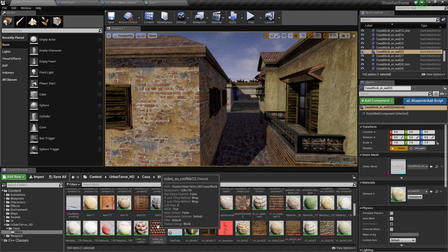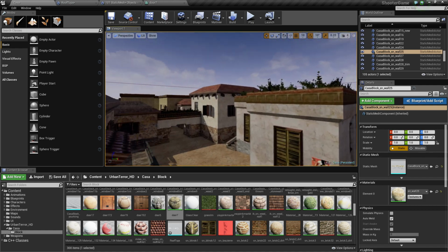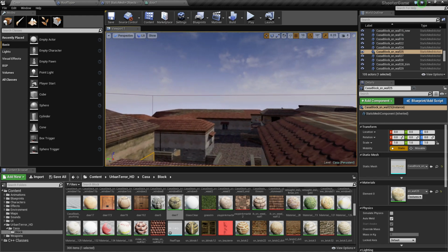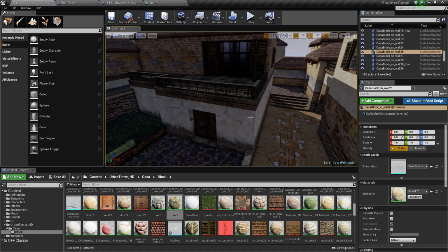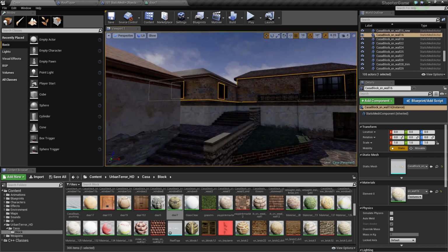What I plan on trying, to see if it's going to work, is to convert all the major wall surfaces over to a texture atlas, which means that all these half a dozen textures and materials on this wall here and this wall here are all contained on a single texture, which will drop the draw calls down even lower. So it's only rendering one texture.